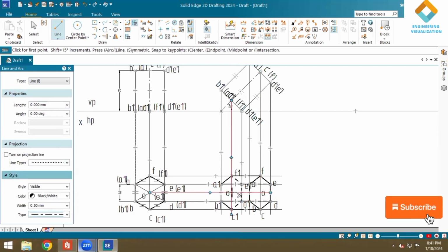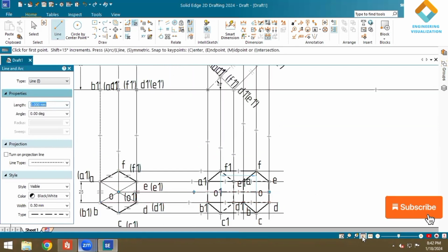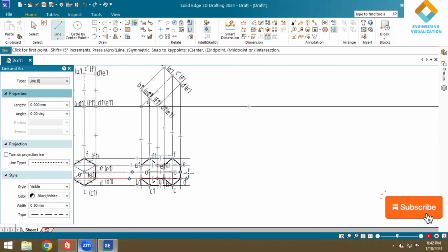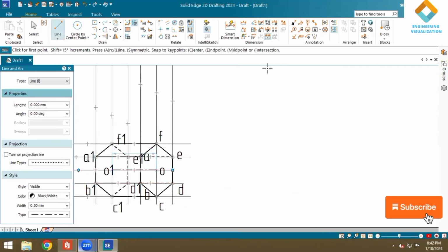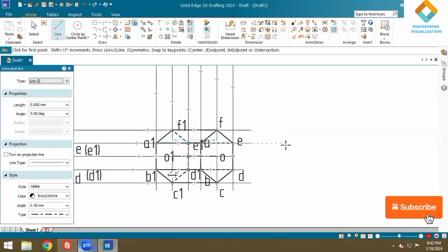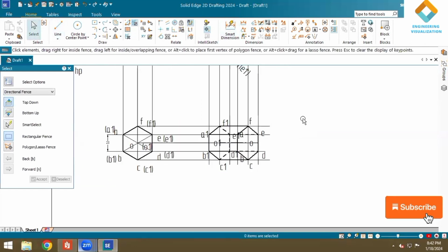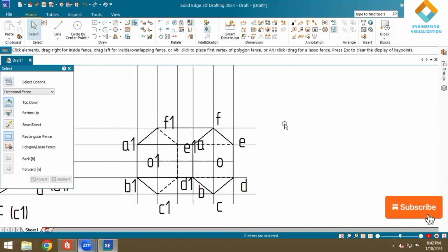Finally, there is an axis you can connect. Okay. Now in this problem, you just see they have given the angle of inclination to the axis for both HP and VP planes. We know the concept for beta angle. If the angle of inclination is given with respect to the axis for both HP and VP, it means it is the beta angle. Correct?